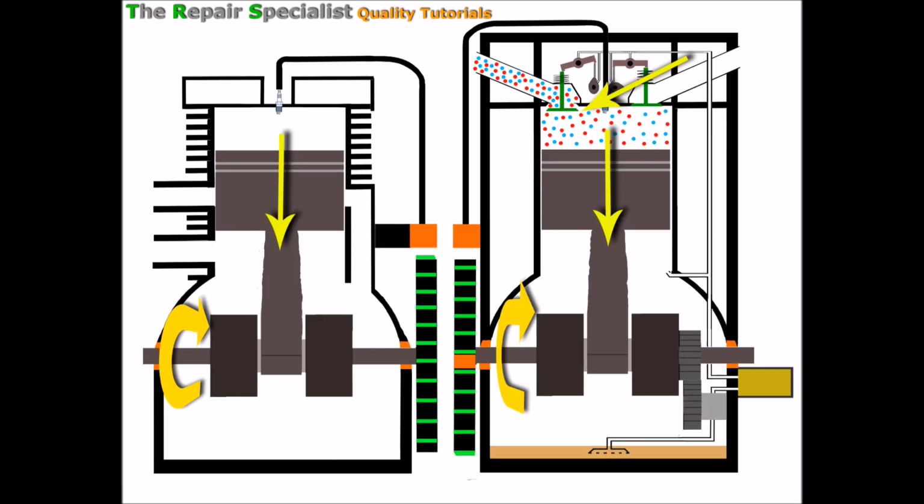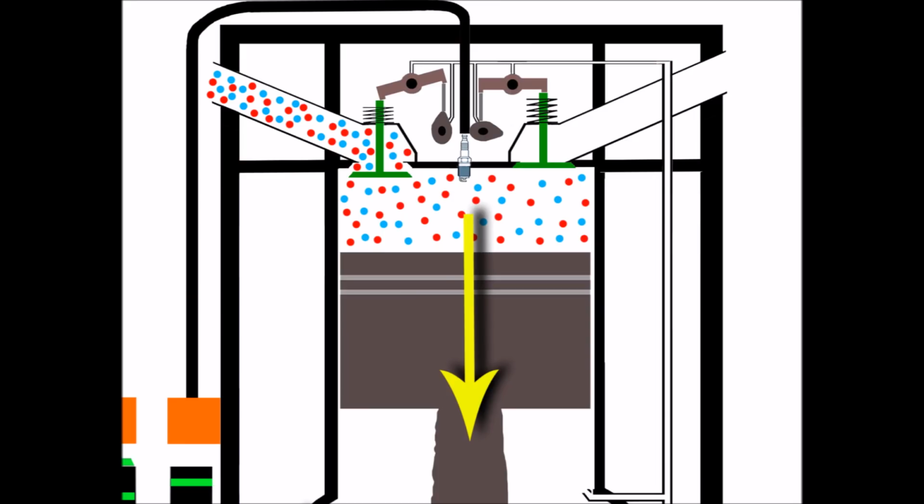Now the way that it opens is by the turning of this cam. And although I haven't illustrated it here, the cam is part of a camshaft which is timed up perfectly with the turning of the crankshaft of the engine. So when the crankshaft is at a certain position, moving the piston downward, it would then turn the camshaft, allowing the inlet valve to open. And in order for me to explain that a little better, I'll zoom in just on this area here.